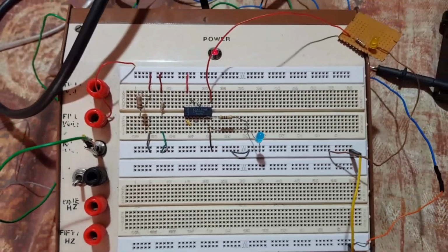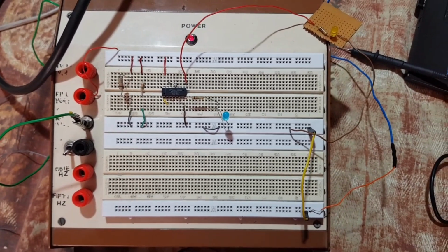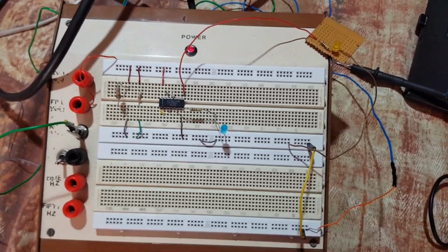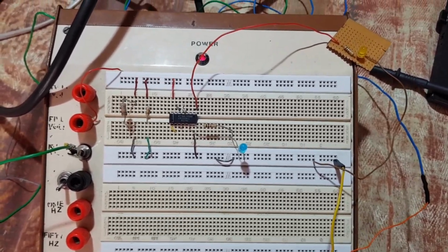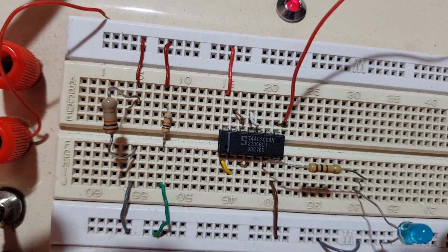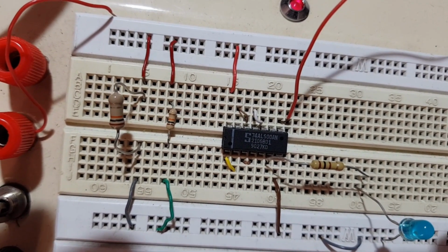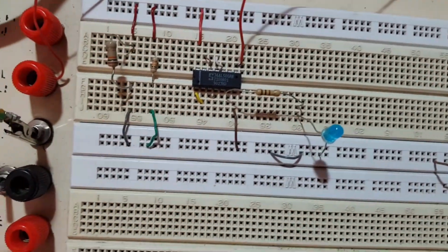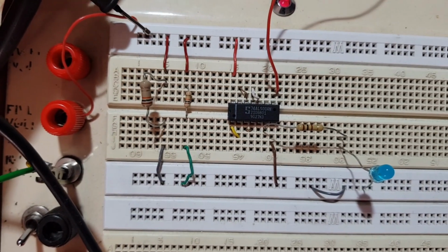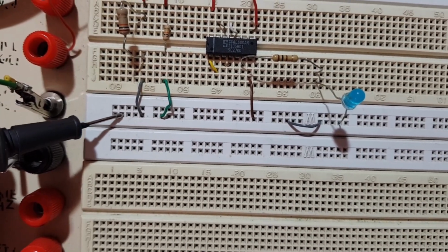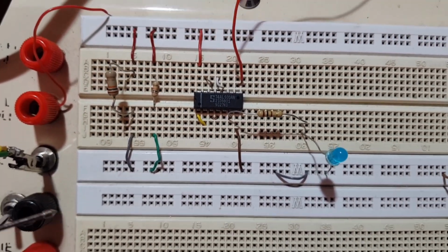So here I have all of the components laid out on a breadboard to visually represent what I just talked about in the diagram. You will see, if you look closely here, I have two 10K resistors coming from my input terminal here at the top. Let me just point it out. This is my positive input terminal where the 5 volts comes in. Here at the bottom terminal, I have grounded everything.